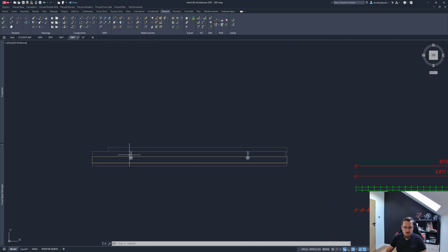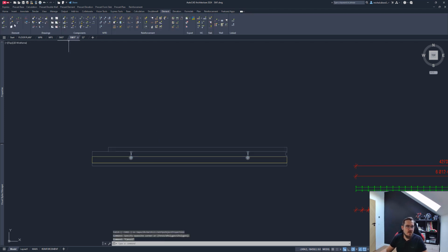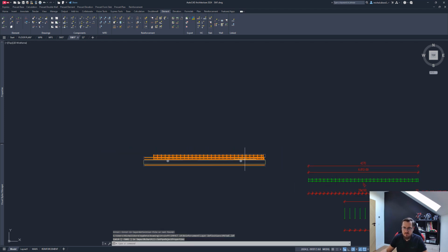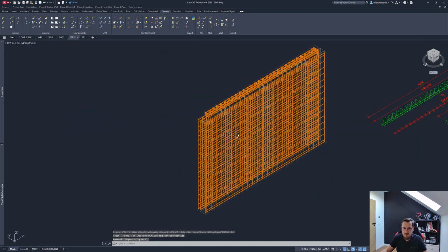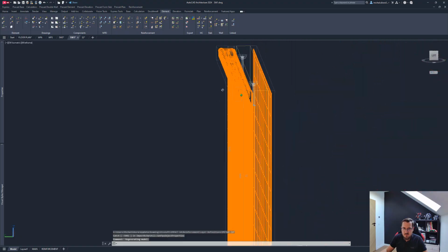Now in here, as was the case for the columns, there is a 3D model of the element. I can just click on that icon here. This changes to a solid reinforcement view, and for the preview, I want to include the reinforcement. I want the cast-in material as well. And like that, I have a 3D view of the reinforcement.